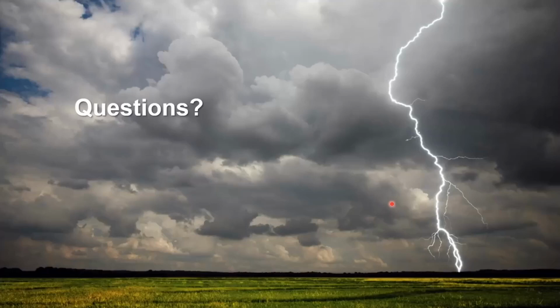Yeah, I think this goes in line with the previous one. I don't know if Andrea or William can give a different point of view, but from my side, I think that in this case the external fault detection should compensate for the possible problems this scenario may have. So it shouldn't be necessary to have a time delay on those elements.